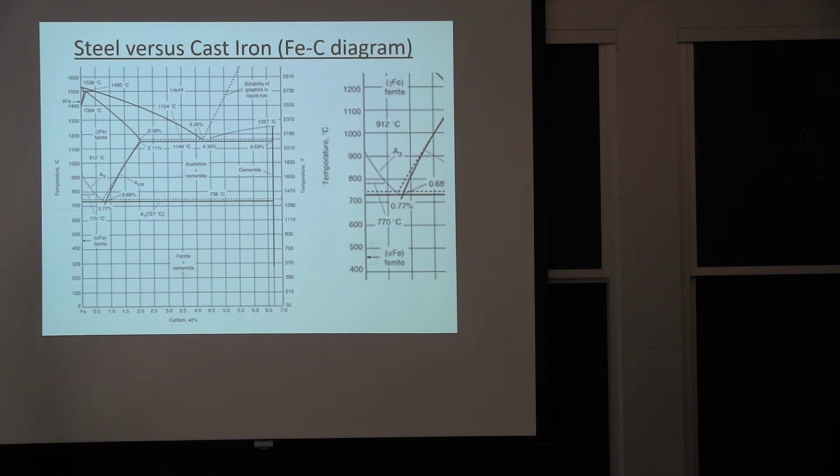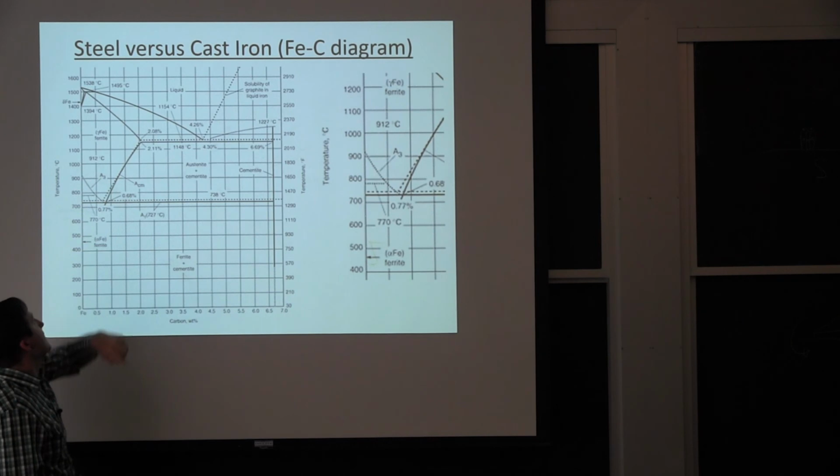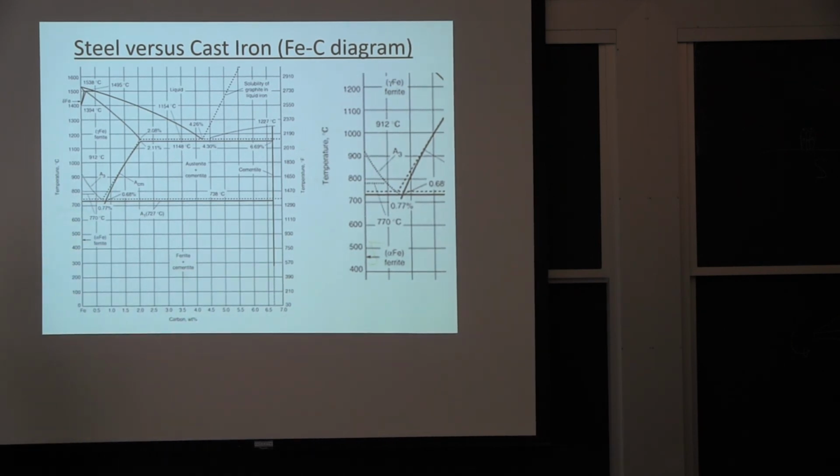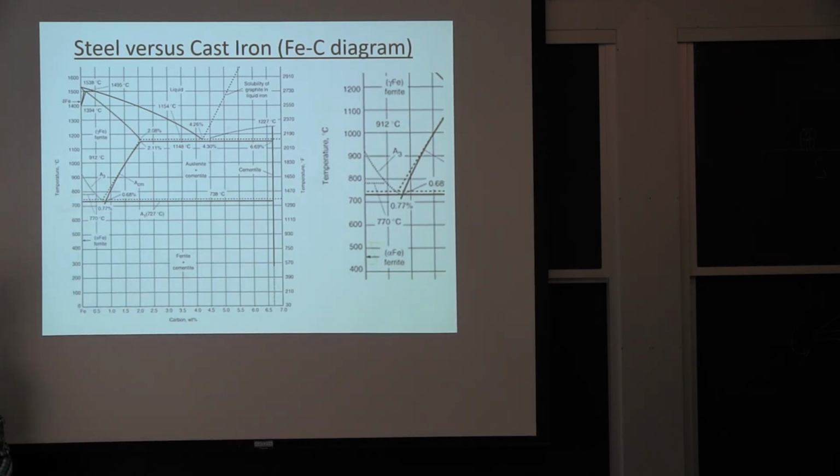So you take the steel, you heat it up until it's really red. That's this phase here, that's the austenite steel. And then you cool it down quickly by quenching it in water or oil. In some alloys, not so much steel, but in some alloy you can also just use airflow to cause enough cooling for quenching.